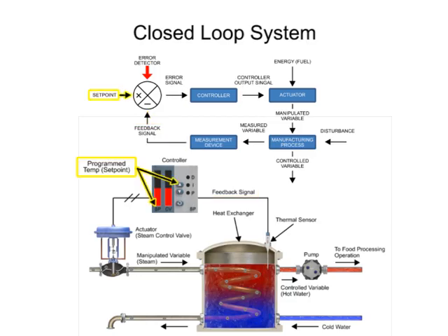Set point is the predetermined value of the desired condition of the controlled variable. In the heat exchanger, the set point is the programmed value of the water temperature leaving the tank.